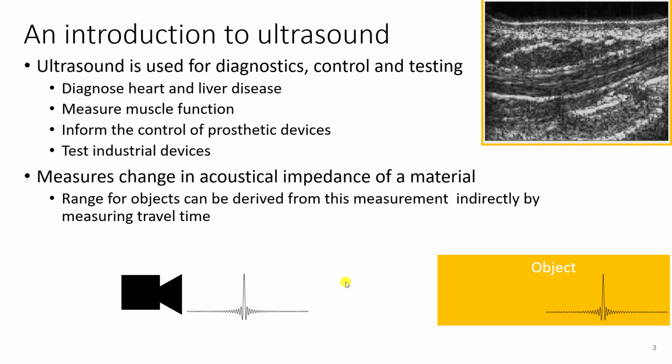Now, if we know the speed of sound in the medium, we can compute the range of this object based on the time it takes for this pulse to have come back and been received by the transducer.